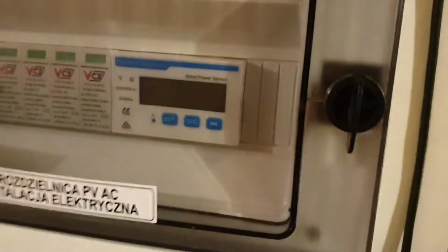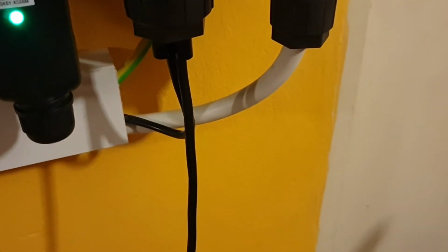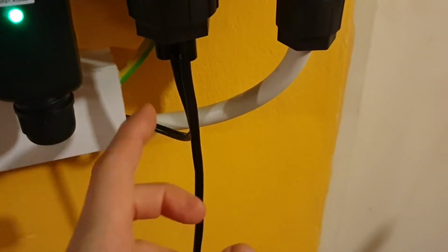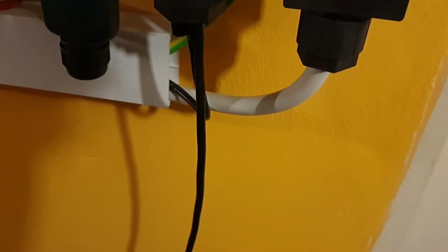So what is also interesting, we can use a built-in power meter here, so the built-in solution from Huawei, but we are also able to connect some other power meter for that, and we can connect it in parallel on the same cable, because for the Modbus protocol, every device has its own unit ID.